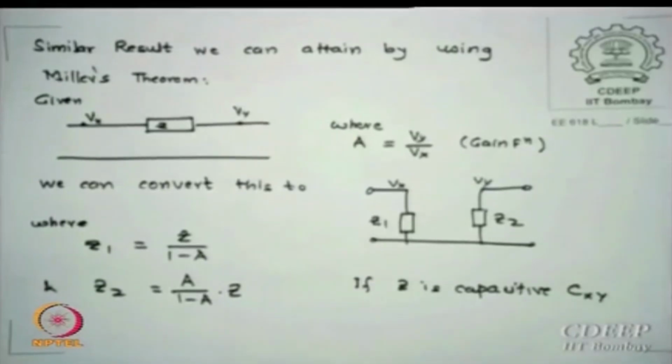That is why it is 1 plus gain times the C has increased. Is that point clear? 1 upon omega C is the impedance. So C becomes lower and therefore net capacitance actually increases. This is very important. Most of you know this working well, but here is a problem which you should all know. Miller's theorem cannot be applied randomly, which is why an example is given.